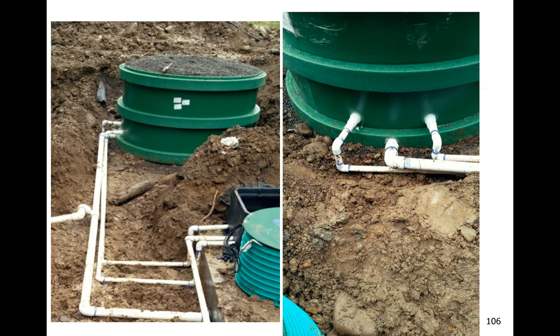And going back to the previous slide, you can see the headworks has the 3 outlets. One's to the coil, one's from the coil, and again they go back and attach to the tank adapters. And the middle one, which is B, is going to come around and go back to the inlet of the tank. That's the flush line, or we call it the vent line, for all the flush water for the system, which will come back into the inlet of the tank. And again, this is only for the low flow portion of the system.